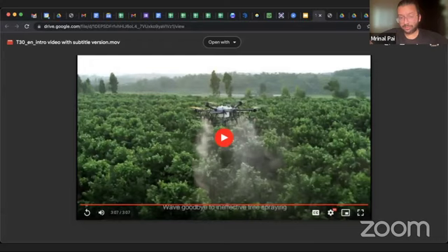With drones, 1 acre gets sprayed in 10 minutes in one flight, and does not require 200 liters of water; for 1 acre it requires about 20 liters, 10% of the water required to spray these pesticides, these chemicals, effectively. And also the concentration of the usage, the dosage of the pesticide or the chemical in any form, is reduced by close to 25% to 30%. So the cost saving per acre,